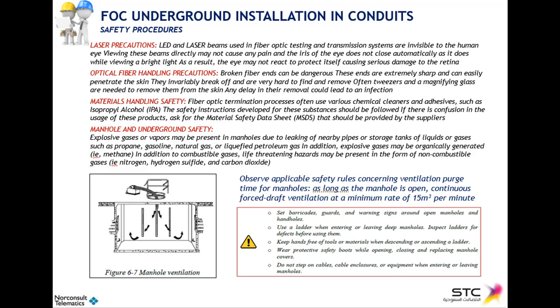Another important point here, although it's not directly related to the cable installation but more to the additional procedures, is when you are accessing a manhole. A manhole is supposed to be big enough to host a person inside, and manholes may accumulate different types of gases. So it is mandatory, and this is a very important point, please apply STC rules on accessing manholes. That is, right after you remove the cover, you have to force ventilation at a minimum rate of 15 cubic meters per minute.